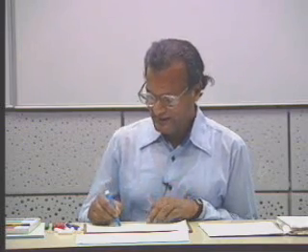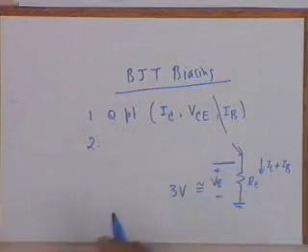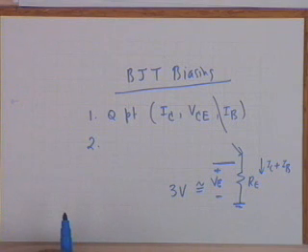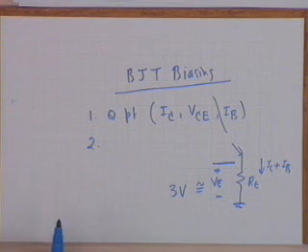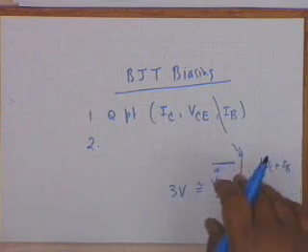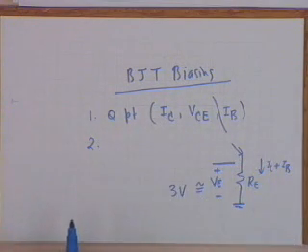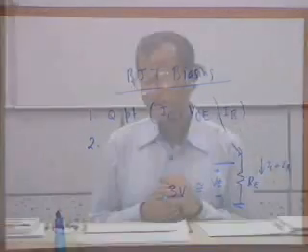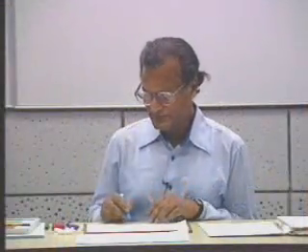One of the things that textbooks or manufacturers specify is arbitrarily choose VE equal to 3 volt. Now suppose this transistor is to go into a space instrumentation, into a space vehicle, where voltages available are very small, maybe 1 volt is the total voltage available, then obviously this will not do. You will have to change the design appropriately, maybe 0.3 volt. But for normal operating conditions, 12 volt supply or 15 volt supply, you assume VE approximately as 3 volts. This must be done with care.